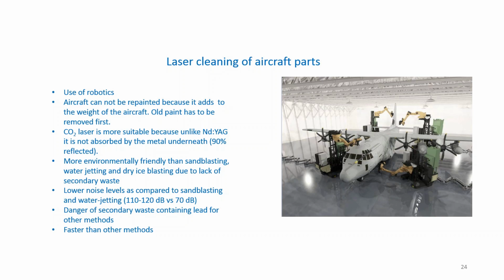And then laser cleaning is fast. So the fact that we said CO2 laser is preferable here was just based on the fact that the metal reflects the mid-IR and the paint absorbs mid-IR very well.